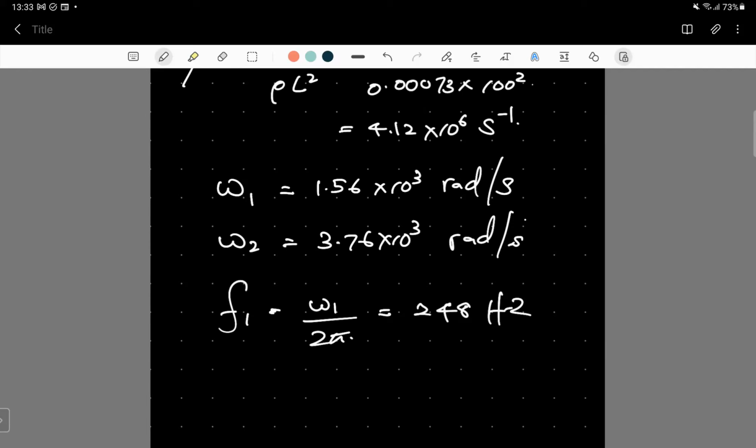So what lies in the low frequency range is considered to be important. So a rule of thumb is to use 2 times as many elements as the number of frequencies desired, if we want to calculate, let's say, natural frequencies of a bar.